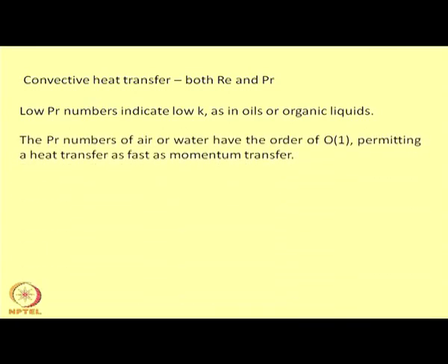important, and where the Prandtl number is going to be of the order of 1, which would tell us that the process is as fast as in momentum transfer, but a different situation would arise when we are dealing with liquid metals. The liquid metals will behave completely differently in the case when we talk about the growth of these layers.